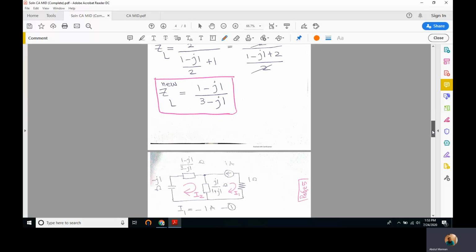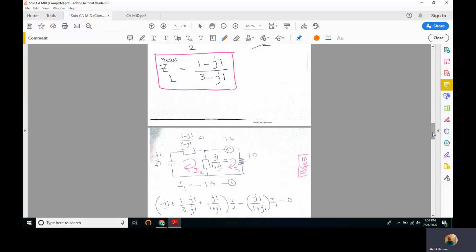Since we have to compute the new power factor in this new load, we have to find the voltage across it and the current going through it, and then we will compute the cosine of the angle between the two to get the new power factor, right?